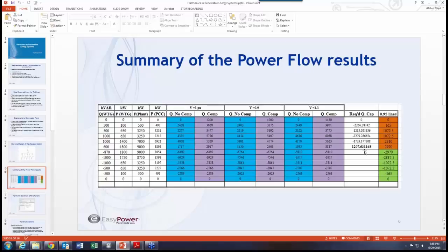So these have all been covered in the past with details. I'm just reviewing them here, that you would need to add this much cap bank to your system. For the rest, we have no deficiency. If we did, that would have been a deficiency in terms of reactive power, which means we would need to calculate the size of a reactor, but there is no need for that.